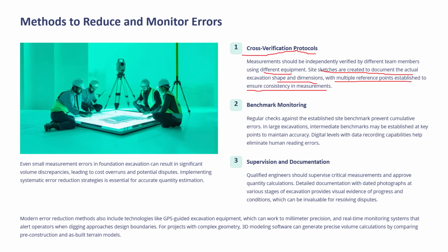And you can employ benchmark monitoring. So regular checkup against the established site benchmarks prevents cumulative errors. In large excavations, intermediate benchmarks may be established at different key points to maintain accuracy. And in today's scenario, digital level with data recording capabilities helps to eliminate human reading errors.